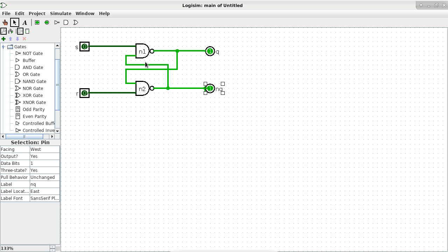Okay. So if you want to understand what a node is, because the node concept is used a lot in circuit design, one thing you can do is to switch to the pointing tool or the poking tool. When you poke something and it becomes bold or thick, that is one single node, representing one single electrical connection. This particular node so happens to connect 3 different points because it connects the output of N1, it connects the pin of Q, and it also connects to one of the inputs of N2. So that's the concept of a node, N-O-D-E, in electrical design.